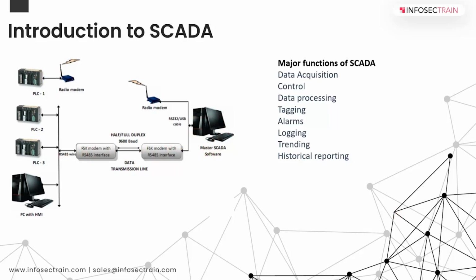So the reason why we have PLC, DCS, and something called SCADA was that SCADA is positioned on top of the hardware to which it is integrated. It will allow the operator to monitor the equipment status, and based on that the operator can control the process. So the operator sitting here can see all the different locations, the parameters of the process, from a single control room.